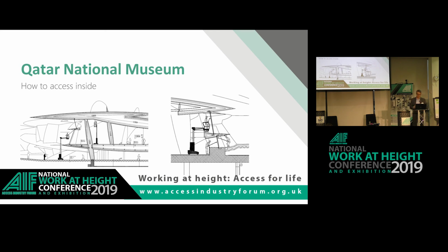That was probably the most complex because we had all the glazing that sort of leans in at an angle. Some of it leans out. Some of it was so low you couldn't even stand up in it. So you can see down here, you couldn't even stand up in some of this. So we worked with the architect to try and design this out as much as possible. But we didn't completely succeed on this. We did a schedule of all the glazing and we got to a situation where I think it was something like 97% of all the glazing you could access, you could remove it. And there's still some problematic glazing in this project. So if you ever get called there, don't look at the 3% because you're not going to get it out.